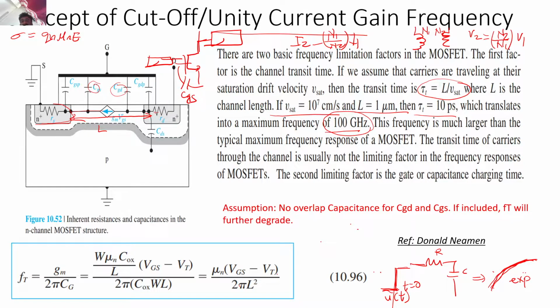And the impedance of the capacitor is nothing but 1 upon j omega C. So as you keep on increasing the frequency, this impedance is going to come down. Now the gate, which had such a huge impedance that no current could flow at the input, will start seeing a low impedance and current will flow at the input.